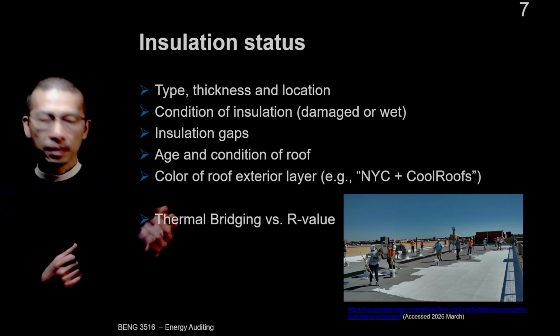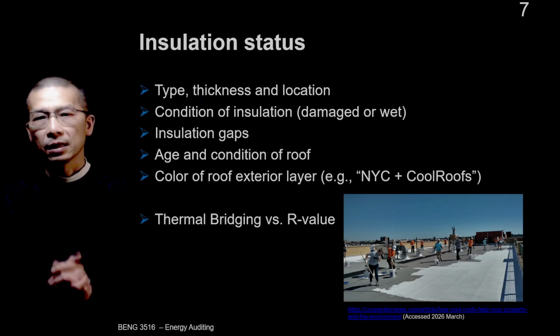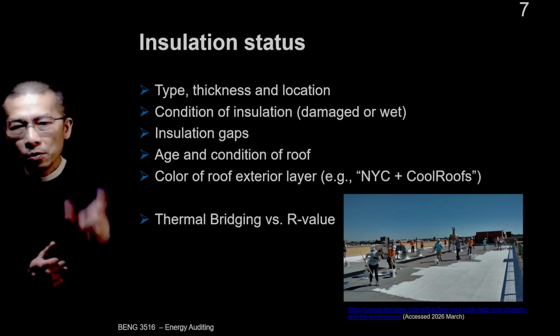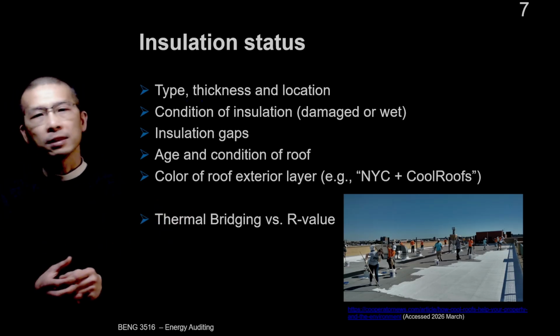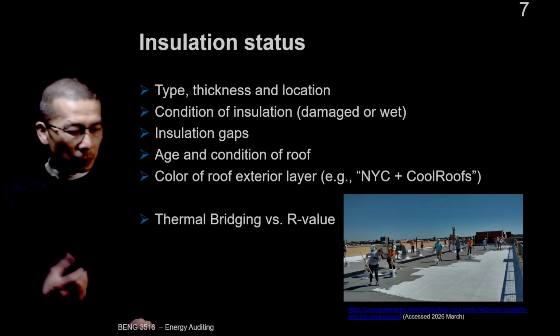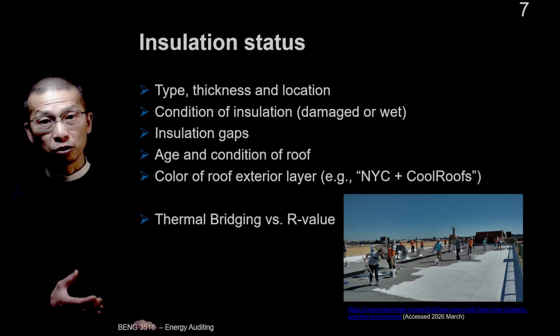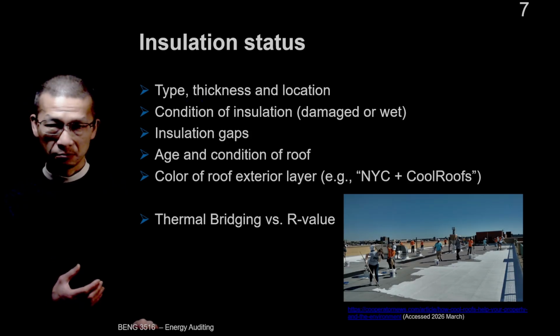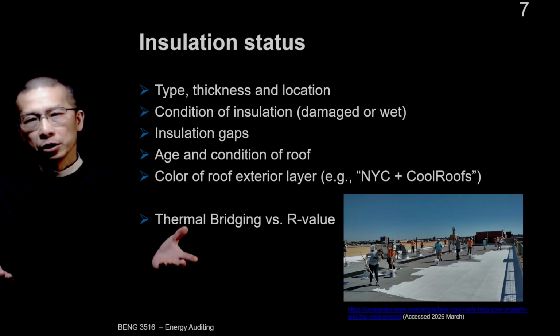Also, we look at if there's any gap. Even a small 5 or 10% insulation gap can reduce the effective R value of the wall by as much as 50%, right? Very small area. It's like thermal bridging again.